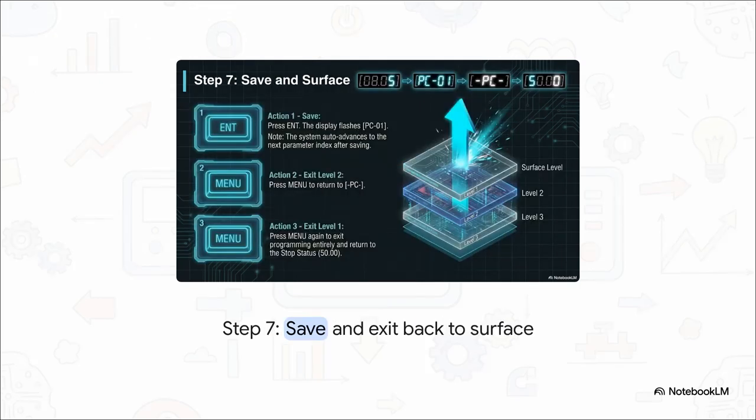Mission accomplished, but we gotta secure our changes and get out of there. We press ENT to save the new data. The system actually auto-advances to the next parameter, PC01, just in case we have more work to do, but we don't. So we just rapidly press the menu key twice. Each press surfaces us layer by layer, pulling us back up from the depths until we're safely back on the top-level display, seeing our home status.